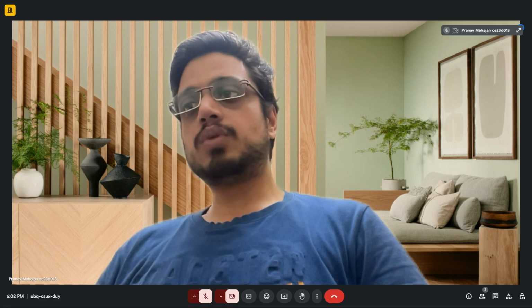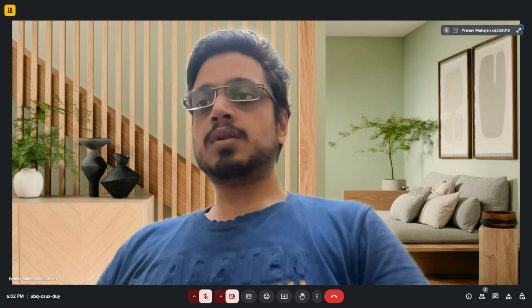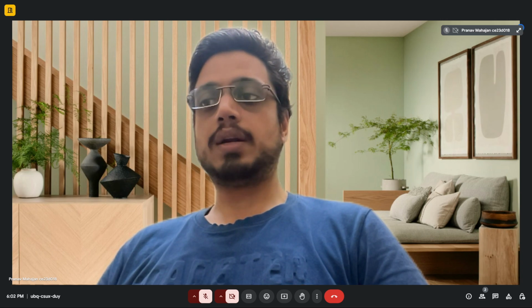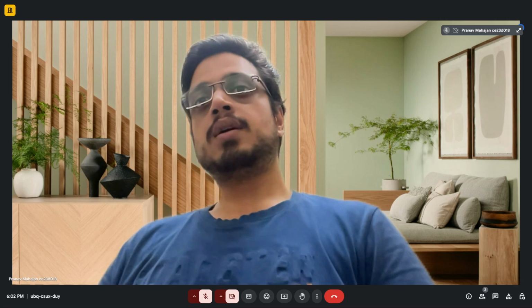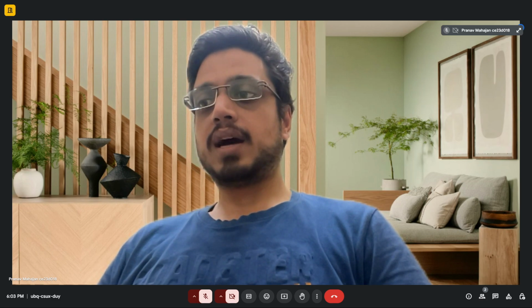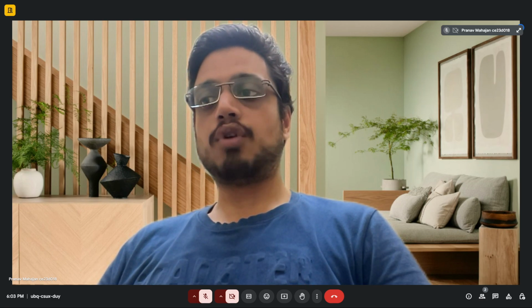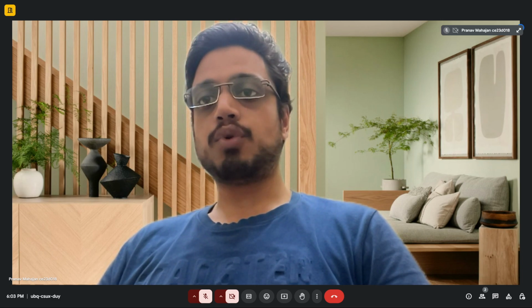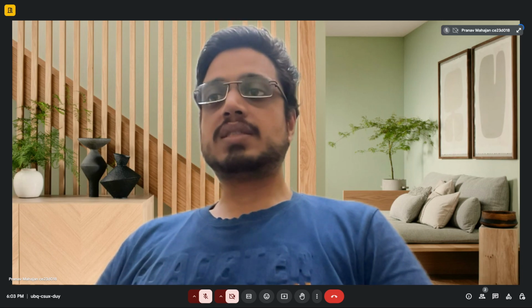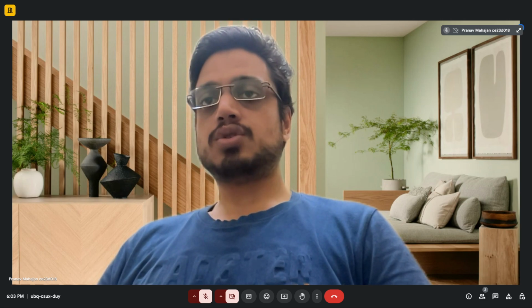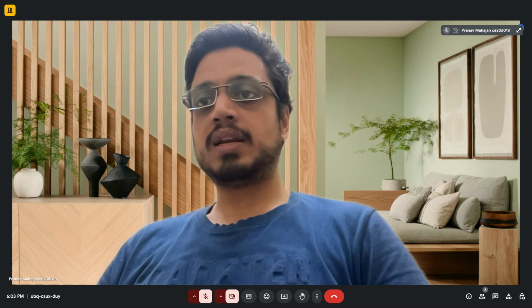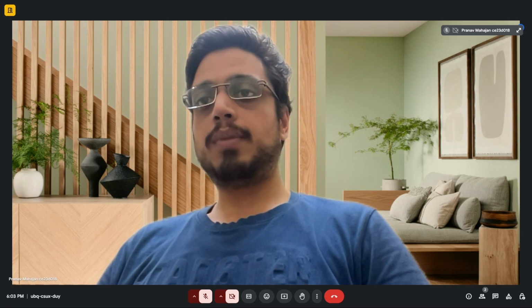So, regarding the previous week, how we have summarized. The class was conducted yesterday as a compensatory class which was not held in the previous Saturday. In that we have seen how we can use method of consistent deformations in determining the unknown reactions, or you can say redundant forces and moments in the statically indeterminate trusses. Whether your truss is of first order indeterminacy or the second order indeterminacy, we have seen through the problems how we can solve them using force method.